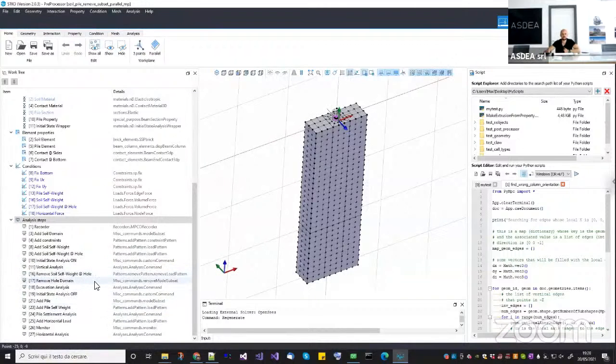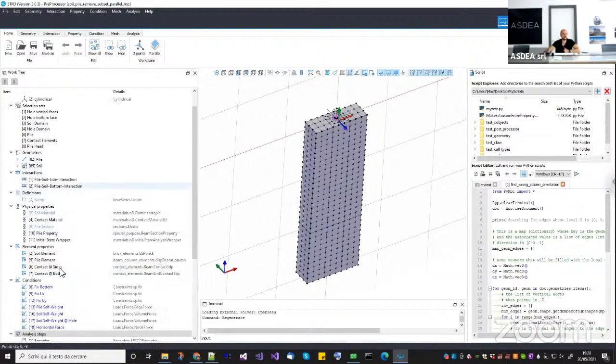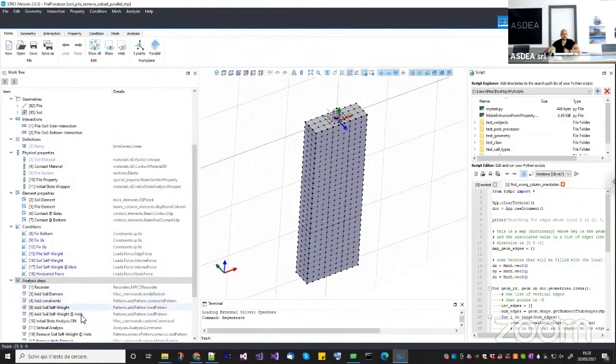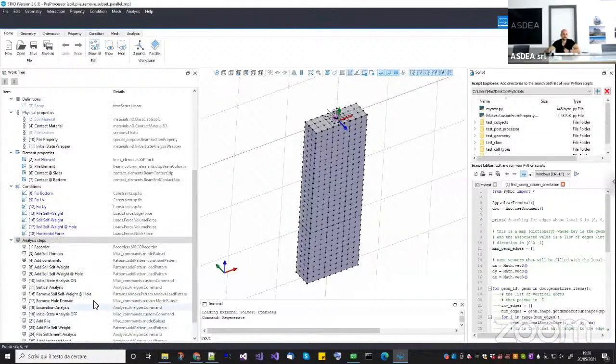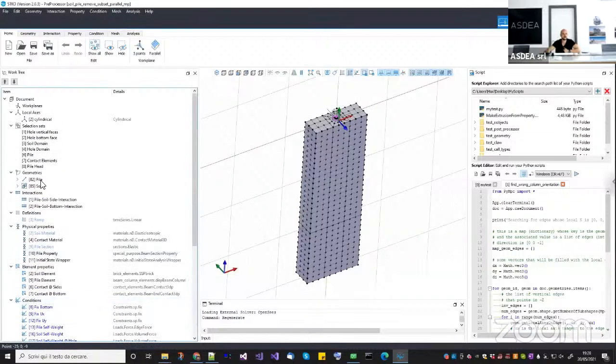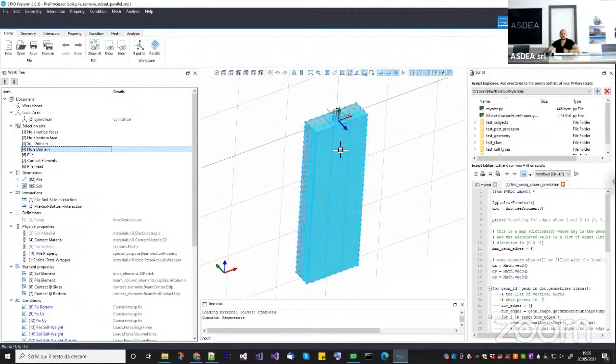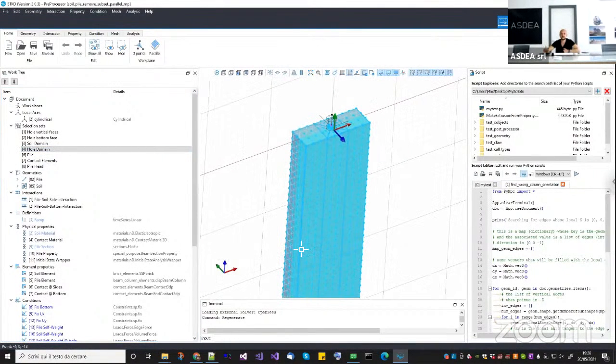You can simulate a step-by-step removal, for example, by creating many of these remove model subset and creating several whole domains, piece by piece. You can try with 3 or 4 pieces, removing from the top to the bottom, and probably it will work. But actually, this is a problem because the removal is done in a single shot and you already have soil